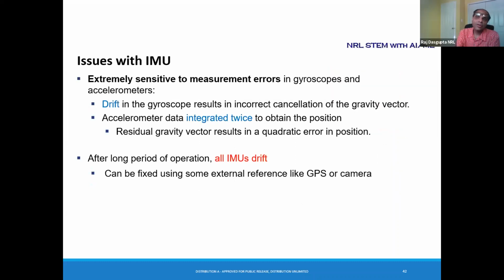I have given some code later on, and we probably won't have time to get into that. But later on, I presume some of you will be able to use this PiMars robot. All of this code runs on the Raspberry Pi. With that code, you'll be able to find out the acceleration and the heading of the robot, and from that, the speed and the distance that the robot has moved.